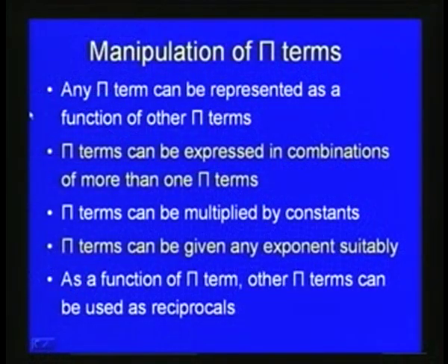And the next point is the manipulation of pi terms. When we discussed the Buckingham pi theorem and saw how to solve a particular problem using it, we saw that some of the pi terms can be manipulated to get an appropriate dimensional form. Some important points as far as manipulation of pi terms are concerned: any pi term can be represented as a function of other pi terms.